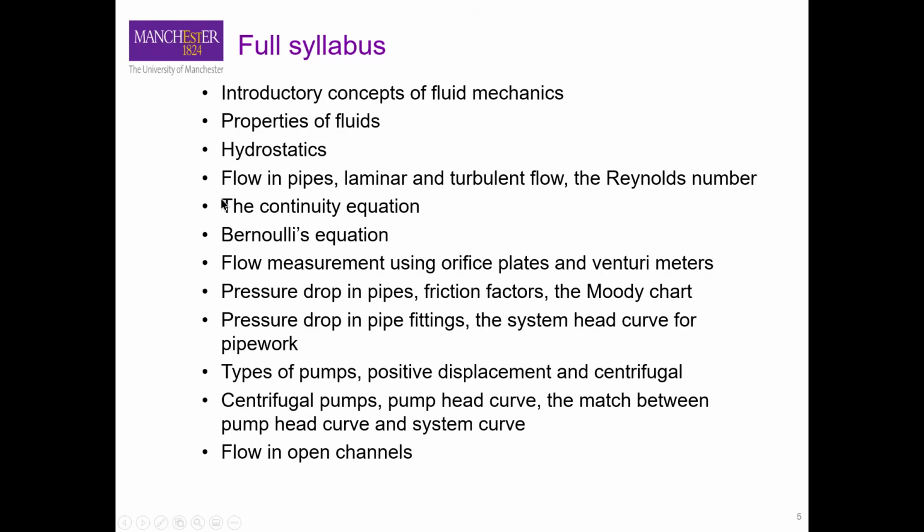Then we will also look at conservation of mass, that is the continuity equation, and conservation of energy, that is called the Bernoulli equation, and how we will use these two principles to measure the flows of fluid in pipes and the pressure losses in pipes and fittings, for example.